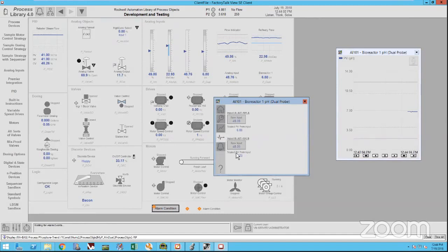So you can see what your raw input coming in. This is something different than the older library. You couldn't see that in the past. You can only see the scale values after the fact. And all your alarms that are pre-built. So this is an analog input, so you can define which one of these you care about. So if your system doesn't have a low, low, high, high, or you don't have a low and a high, just ignore it. You can disable everything at runtime.